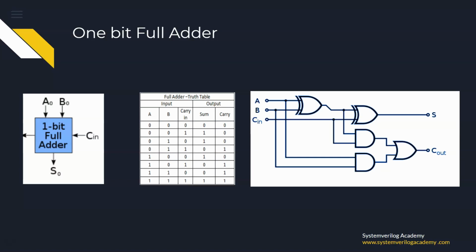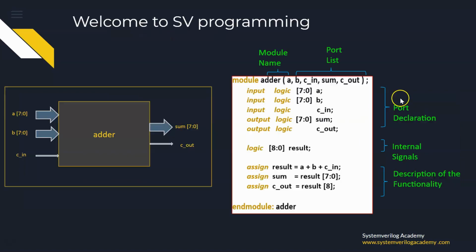But by using a SystemVerilog program that we had seen earlier, like this, you are actually implementing an 8-bit full adder. Here you haven't specified anything about the actual hardware, you haven't specified how the gates are connected, how many gates are used, you haven't given any such directions, but you have just used 3 simple lines of SystemVerilog to represent this full adder.